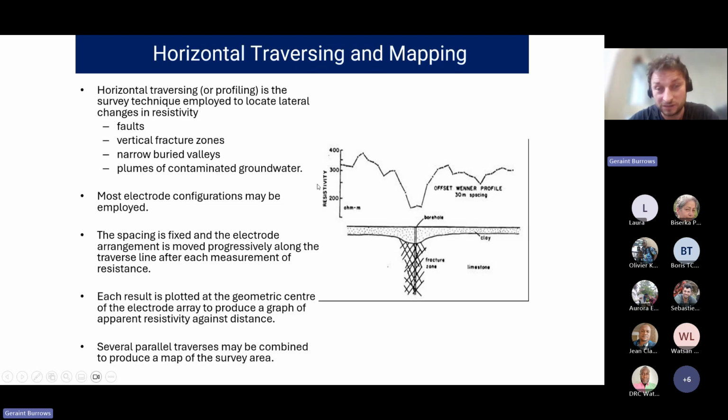Even if you've not got any information on structures passing your point, you would still want to do, let's say the example used earlier, where I think you said it's a hospital with about a 300-meter land area around. You would want to do a constant separation traverse across the perimeters of that land to see if there are any points in that traverse where there is a deeper zone of weathering, i.e. you're looking to pick up areas where your resistivity along that constant separation traverse is reduced.